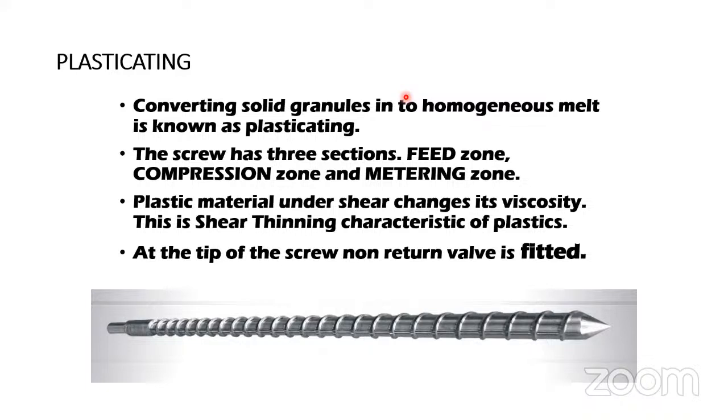Sir, then tomorrow if you can show some table of the mold temperature and throat temperature required for each of the 13 materials you have shown, it will be helpful, sir. Because I will try my best level. Yes, sir, just check up. Delrin and HDPE material we are giving to one supplier. He is not giving a chiller at all.